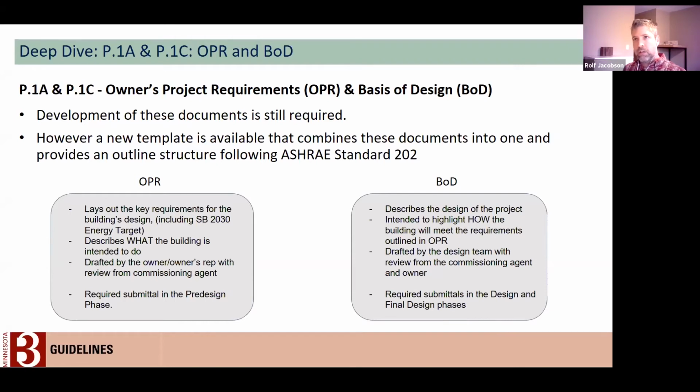And the 1.6 number was selected to basically allow more or less a conventional construction type to pass, as long as low carbon materials were selected for insulation and cladding and roofing. That was kind of the general strategy of the 1.6. The small buildings guideline has been adjusted up from that to 1.75, just to allow a little bit more flexibility for small buildings.